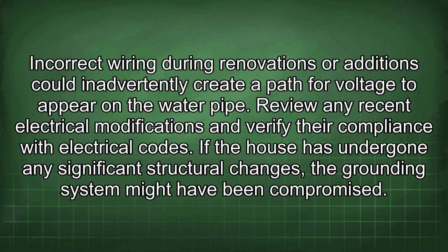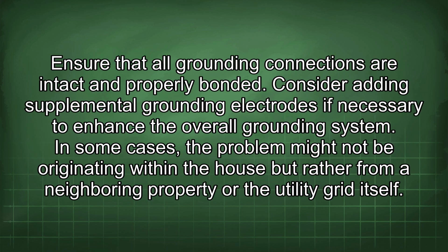If the house has undergone any significant structural changes, the grounding system might have been compromised. Ensure that all grounding connections are intact and properly bonded. Consider adding supplemental grounding electrodes if necessary to enhance the overall grounding system.